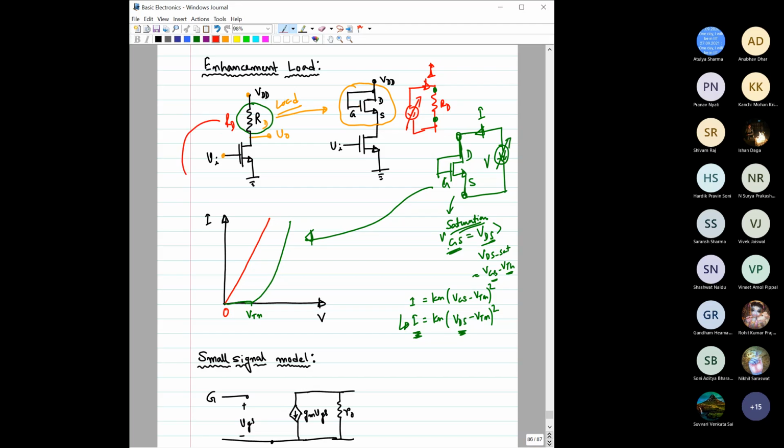So this particular configuration will give an IV characteristic like this, and a resistor would give an IV characteristic like this. You can think that this transistor can also behave like a resistor. Not exactly, the resistor should be a straight line, but here it is parabolic. Still, it shows this type of two terminal device characteristic, which is not very far from the resistor's.